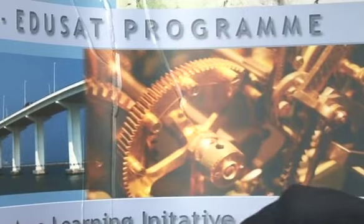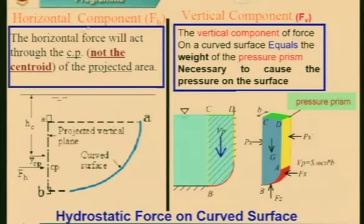Let us go to the next slide. Now we go to the curved plates. Curved plate, as I mentioned yesterday also in the beginning of my lecture, a curved surface will have two components. One will be the horizontal and the other will be the vertical. Is it okay? So the horizontal component will act through the center of pressure, not the centroid of the projected area. Projected area I will explain to you on the board. The vertical component will be the weight of the system from B to C, C to this point, and back to B. So this much weight we need to calculate.